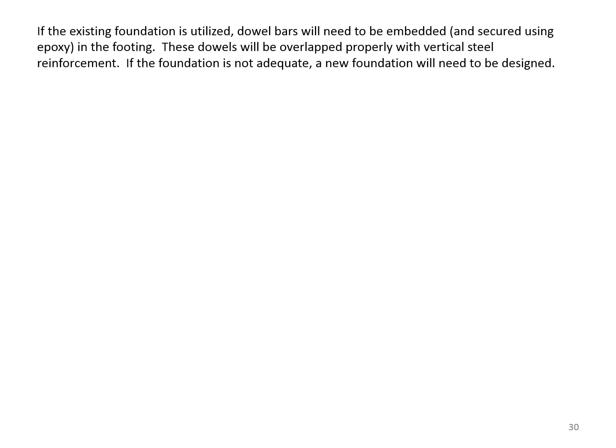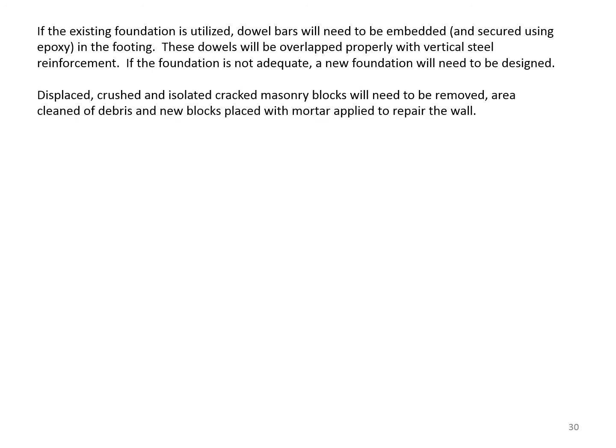If the existing foundation is utilized, dowel bars will need to be embedded and secured using epoxy in the footing. These dowels will be overlapping properly with vertical steel reinforcement. If the foundation is not adequate, a new foundation will need to be designed.